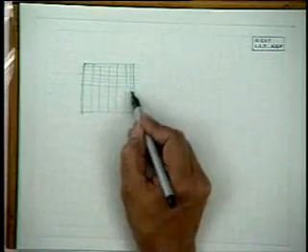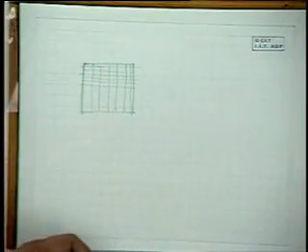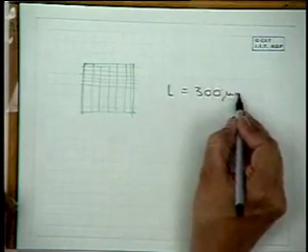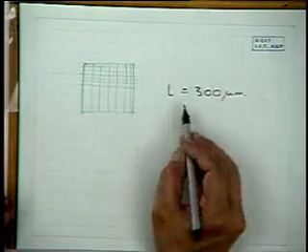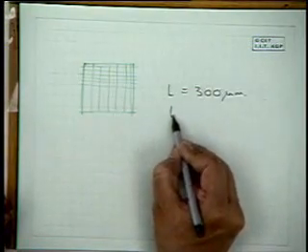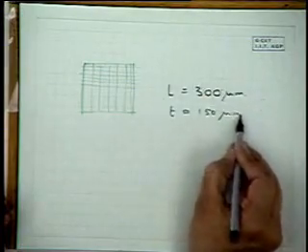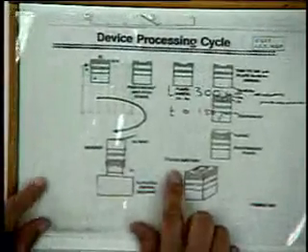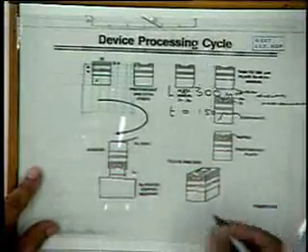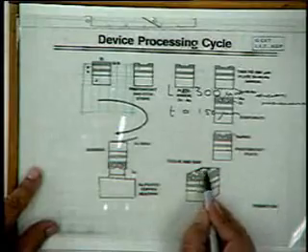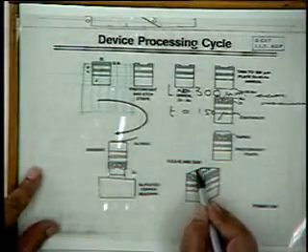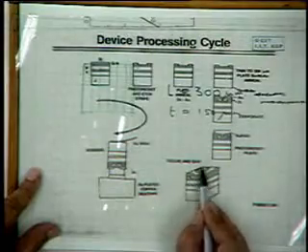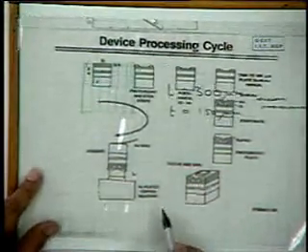into small devices which are typically of the order of 300 microns in length, and the thickness is already of the order of 150 microns, and the stripe width is of the order of a few microns. So we cleave here, and we make the device. These are the bonding pads, on the stripe. Remember, the rest has silicon nitride, which is preventing current flowing right through the device. So this is a stripe geometry, and here comes an interesting step.